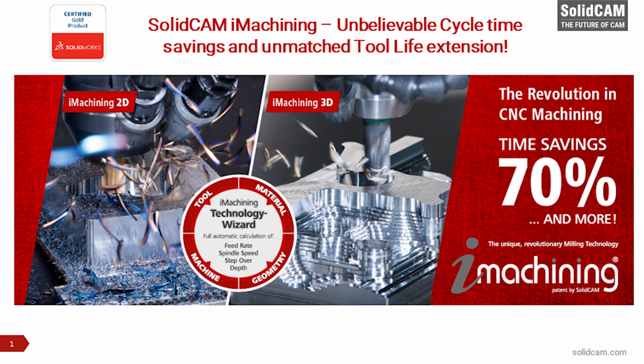And so if you look at carbide, especially the premium carbides that we see today in the tooling industry, they don't handle shock, whether it's a vibrational shock, a thermal shock, or an impact shock. They don't handle that well at all. And so if we can minimize that shock, we improve tool life, we improve performance very well.